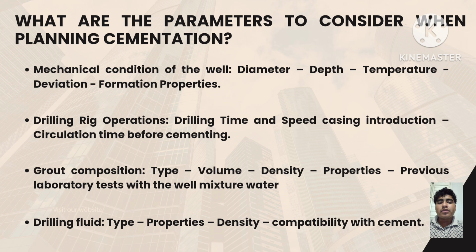Two, cement composition: type, volume, density, properties, previous laboratory tests with the well mixing water. Three, drilling fluid type, properties, density, and compatibility with cement.